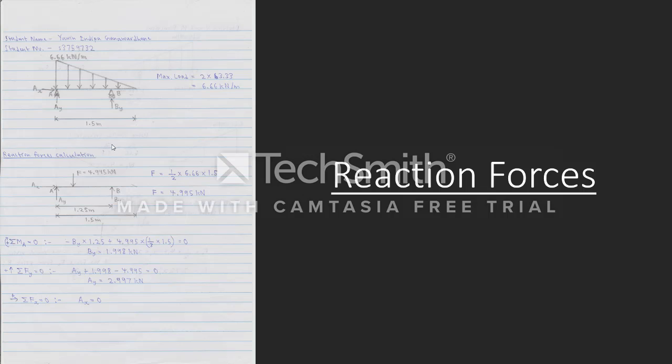I started off with finding the reaction forces of the beam element, which I chose as the roof section of the structure, and I wrote a free body force diagram including the reaction forces, which are Ax, Ay, and By, and also the distributed load, 6.66 kilonewtons per meter on the left hand side and zero to the right hand side.